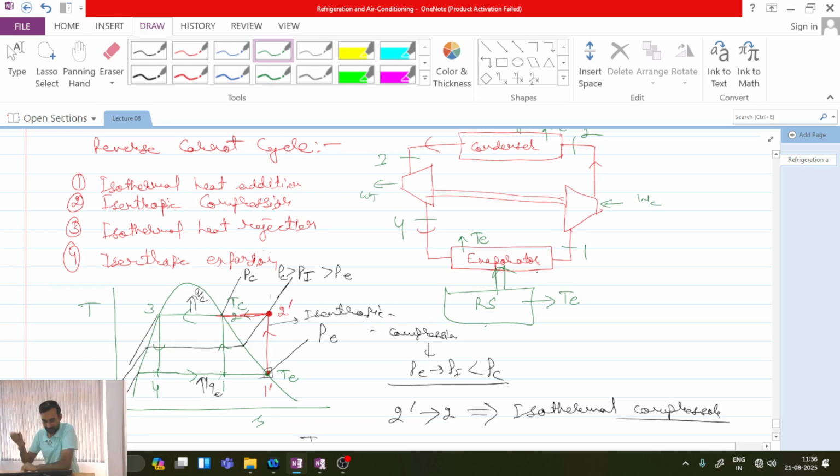Okay, and then I will give another relaxation that heat rejection process is isobaric instead of isothermal, because part of the heat rejection process will be actually taking place in superheated zone, where upon removing the heat, the temperature of the working fluid will decrease. So this will not maintain the isothermal condition, but it will be an isobaric condition. All are clear with this point?